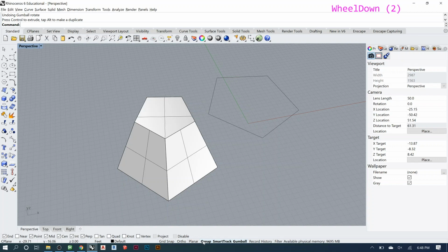So if you do O snap, that's not like it's getting sassy and saying, oh snap, it's object snap. That is what allows Rhino to know when you're trying to snap to objects. See here I'm on the endpoint over there, and right here you get all these different locks that you can either snap to or not snap to.